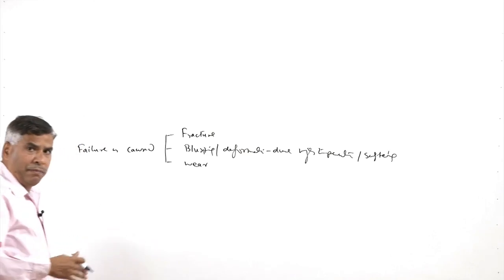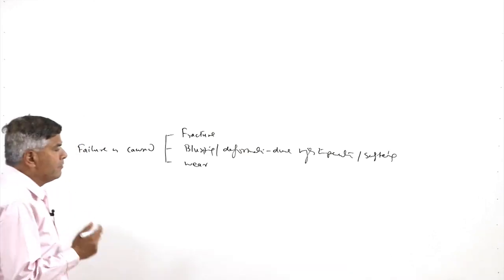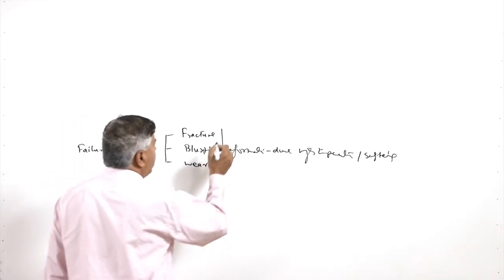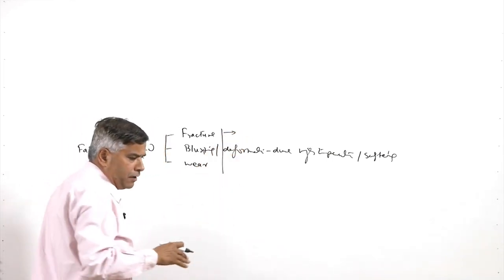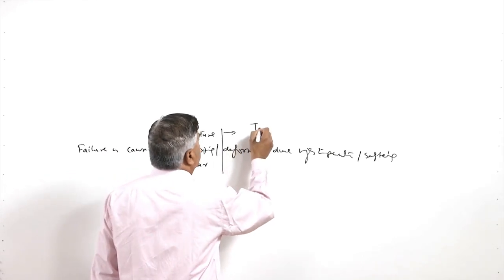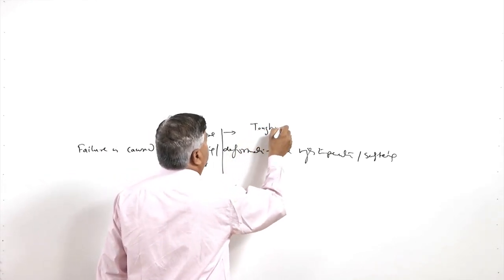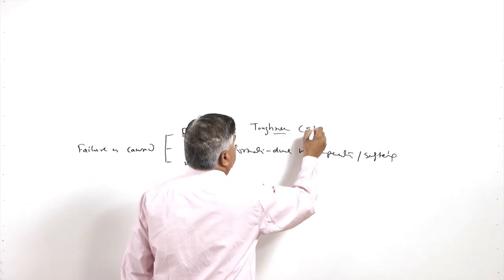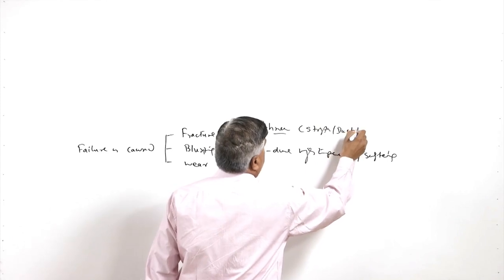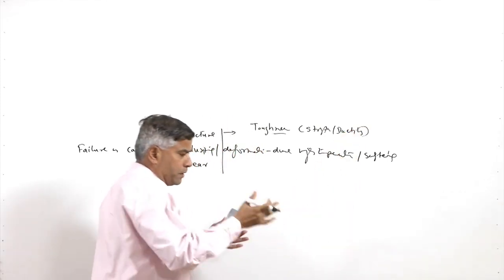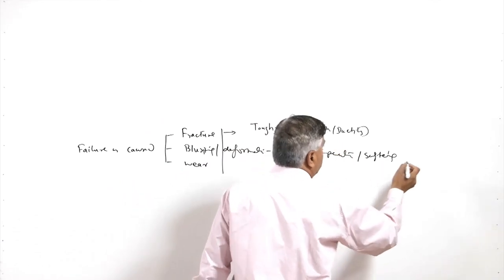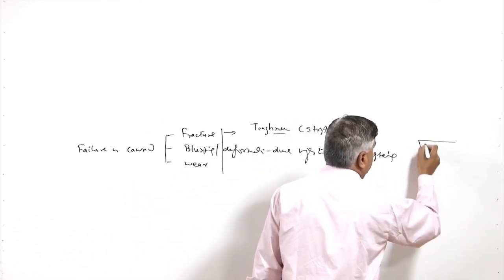So, if we have to make a tool of a particular material, then we will be looking for these characteristics, these properties. To avoid fracture of the tool, it is important that the tool material has the desired toughness, which is a combination of strength and ductility. It helps to absorb the load and the impacts, and so avoids any sudden fracture of the cutting edge.